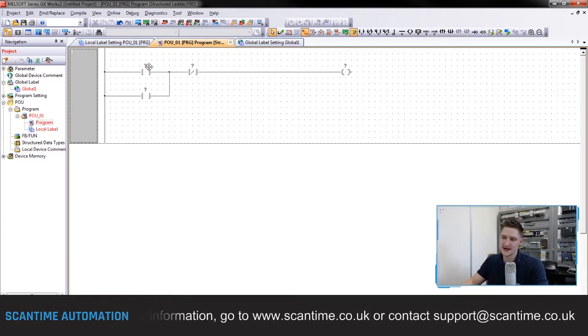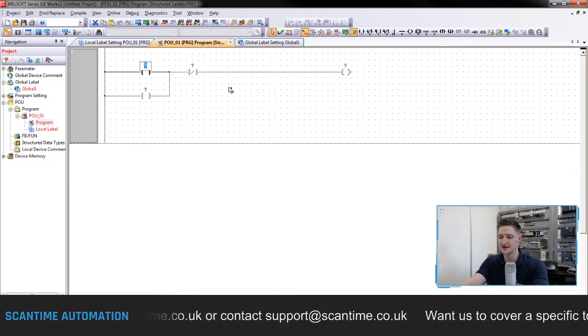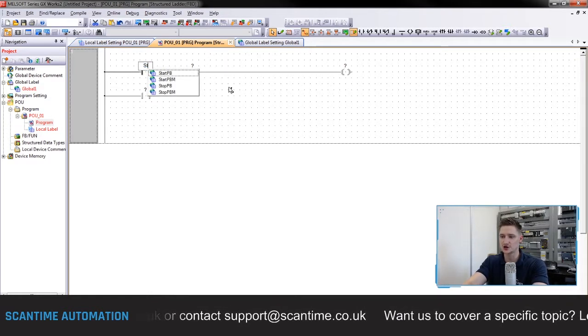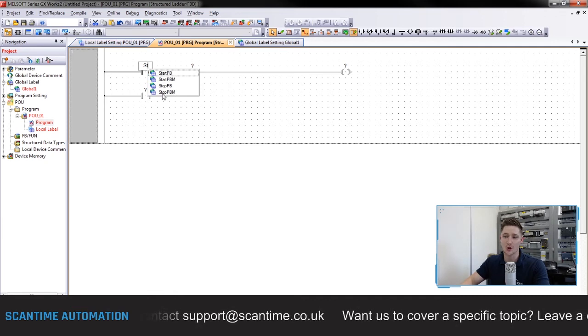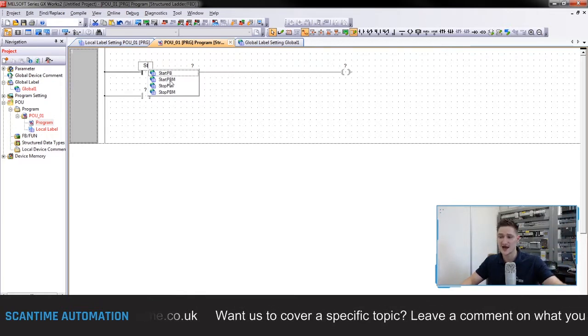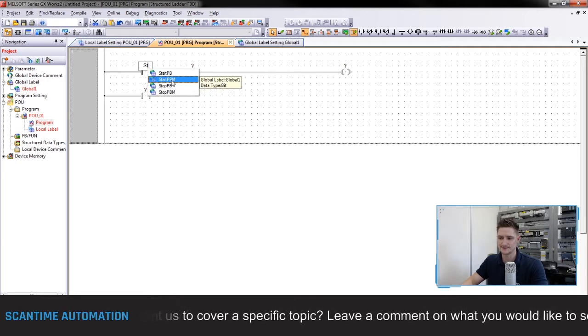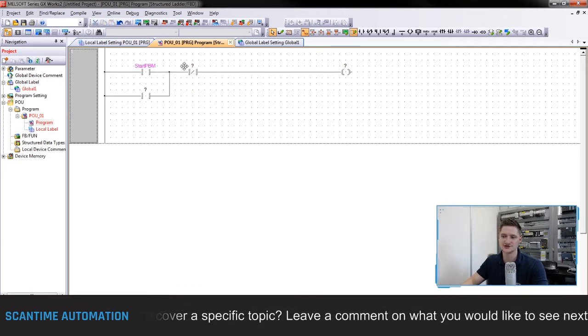Now what I want to do next is assign these contacts and coils to addressing, and to do that, click on the very first normally open contact where the question mark is, and we'll just type in start, and as we start doing that, you can see all of the global labels pop up here. And remember, I don't want the start PB because that's actually wired to the input. I want the start PBM, which is the M bit. Select that. And there we go, and you'll see it turn pink.